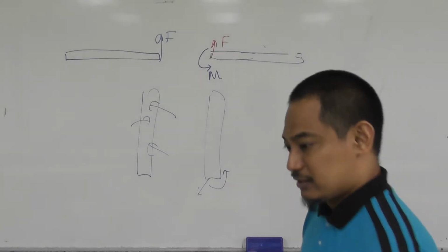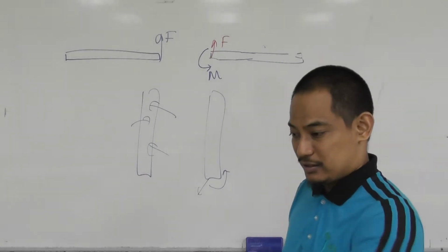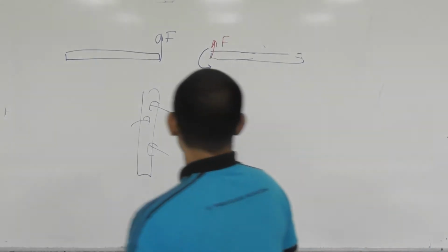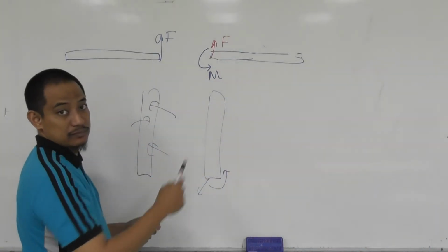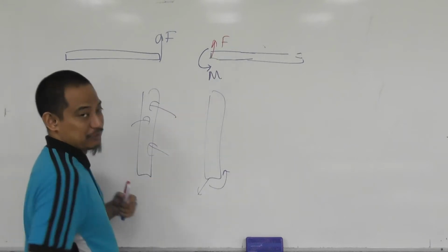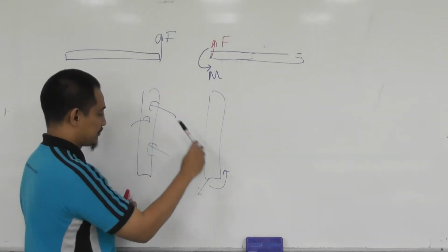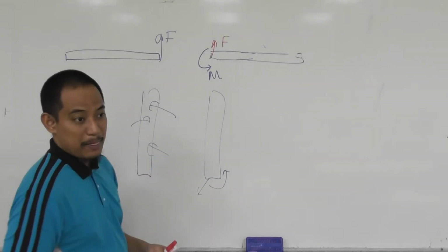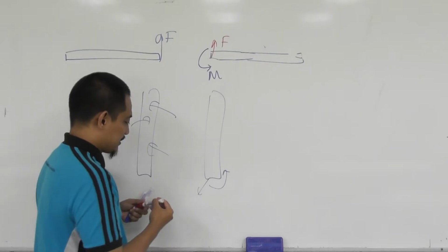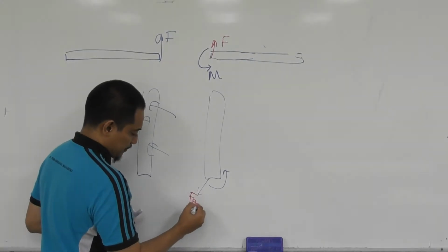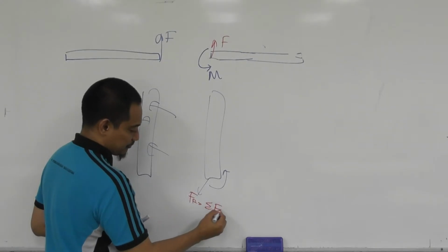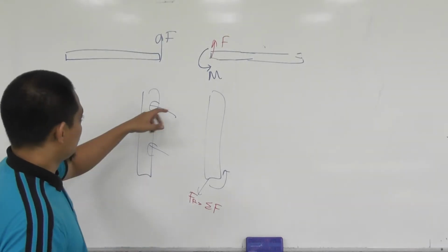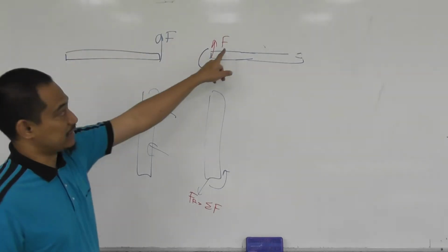And this is why in the slide you suddenly have that equation. Basically, this process here: this F is still the F. When you shift any of these F, it goes here, it's still that F. This one goes down, it's still that F. So in the end, this Fr, the resultant force, is simply the summation of all forces, because the forces never change.